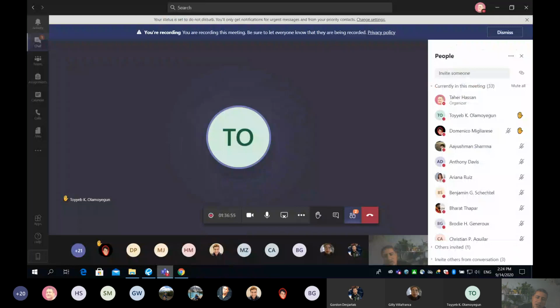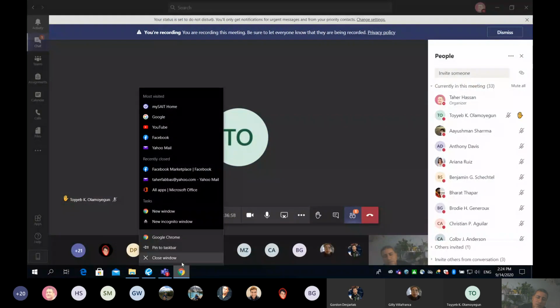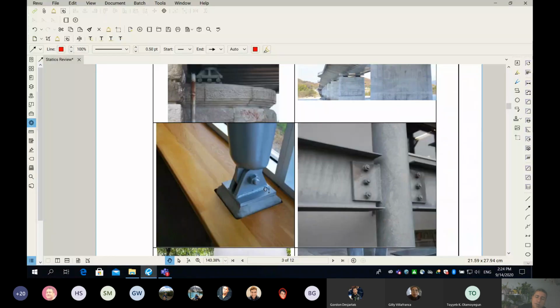So really, this one is a hinge because you can see there is a bolt going in the middle, and this bolt, does it stop rotation? No, it doesn't. The column can rotate, but since we have a bolt, there is no X motion and no Y motion, and it's a hinge. Thank you so much.